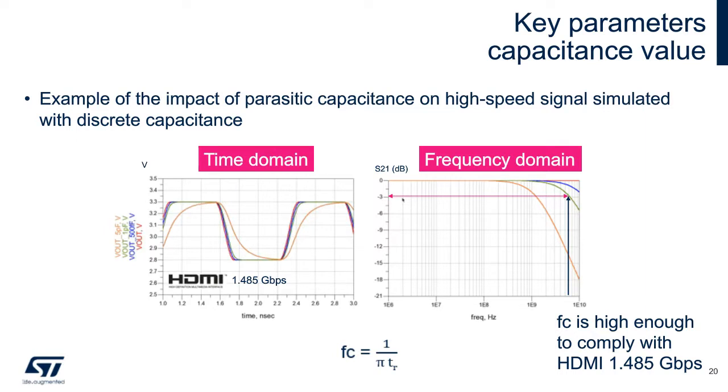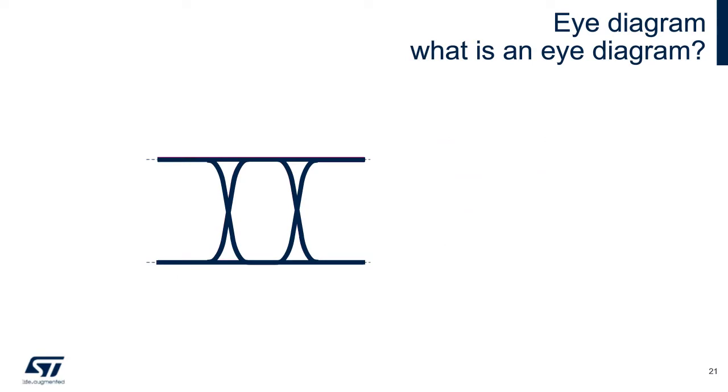Indeed, eye diagram or eye pattern measurement is a tool to characterize transmission quality. In digital communications, the eye diagram is used to visualize how waveforms used to send multiple bits of data can potentially lead to errors in the interpretation of those bits. An eye diagram is produced by repeatedly sampling a digital signal on oscilloscope's vertical axis while triggering the horizontal sweep with the data rates.